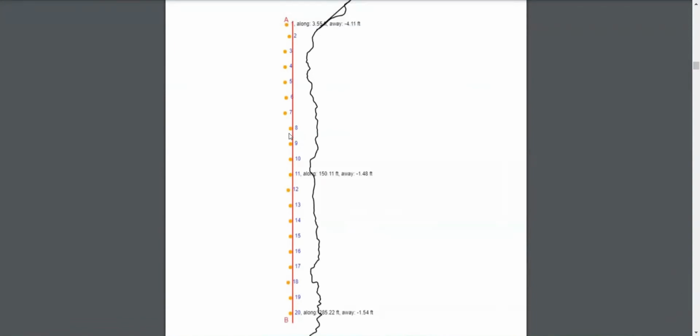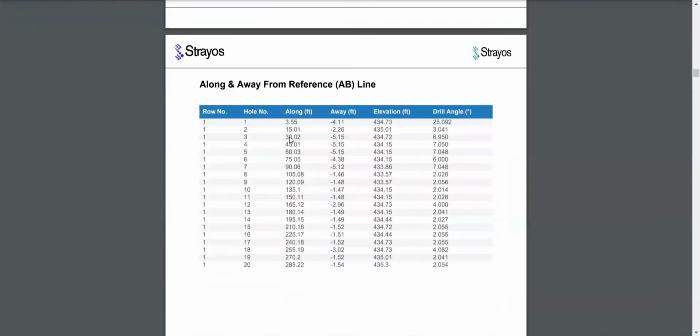Now this page complements the table that's shown on the next page. What we were discussing in one of the previous videos with the cone and the flag is that this model blast can be laid out with just a tape measure. All that's required to do this is having a way to relate the 3D model to reality without a GPS. That's done in this specific case with the cone and the flag on the edge of each AB line that we don't move between the flight and the actual layout.